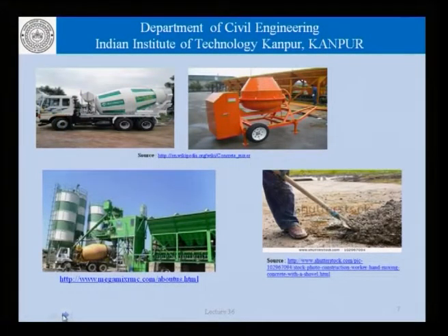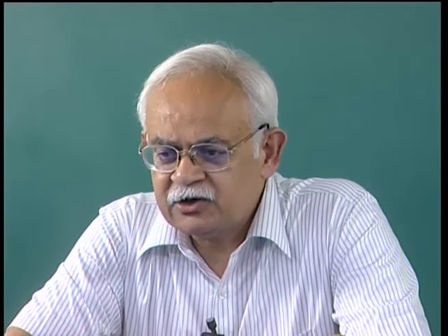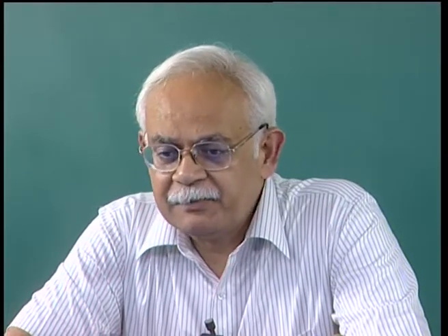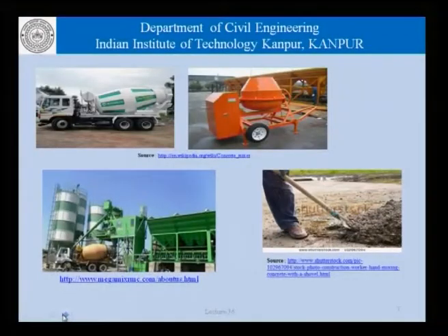Another kind of mixing that goes on in concrete construction, and we must be aware of that, is when the concrete is being transported from the batching plant to the construction site, and that mixing is inadvertent because the intention of that process in an agitator truck is not really to mix the concrete unless it is so designed, but basically to keep the concrete agitated and ensure that the concrete does not set.